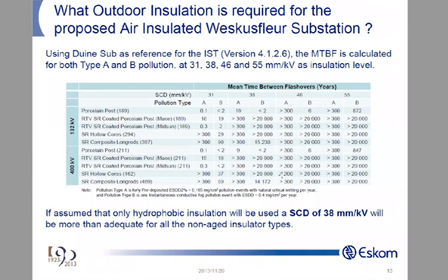So with the coating, you must normally coat between 0.3 and 0.5 millimeters, not much more than that, because once the arc is moving around, the temperature of the arc is not only transferred and causes the alumina trihydrate to go, but the heat is also transferred into the porcelain and sunk into the porcelain. So it reduces the arc root temperatures. So you find that the tracking and erosion on the coating becomes far less.